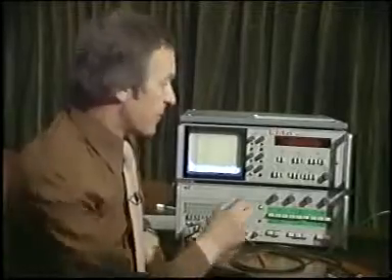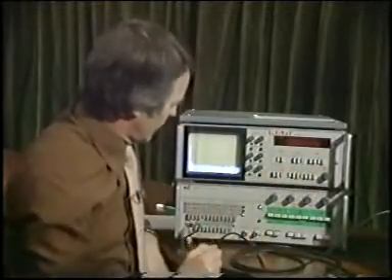Well, this spectrum analyzer is a little different to the one you saw earlier. I'll start it running and see what I mean. Well, just like the other machine, it sweeps from left to right with increasing frequency. But the difference here is that it stores what it sees on the way through as it sweeps. So, horizontal scale is increasing frequency, and the vertical scale gives us the amplitude of the sine wave or frequency components.